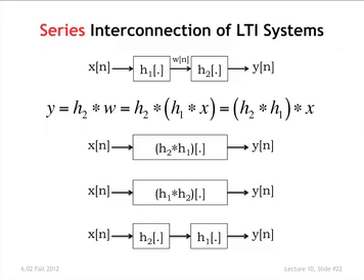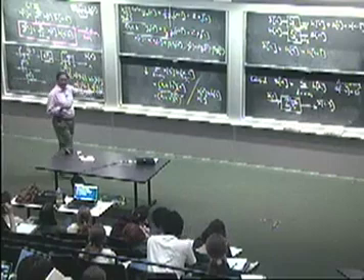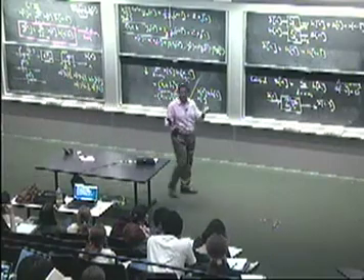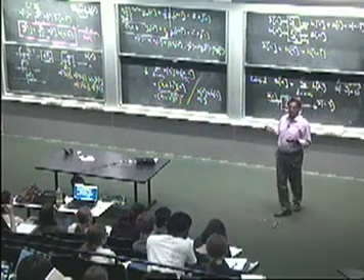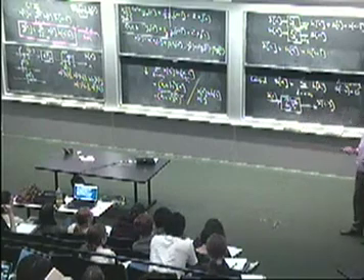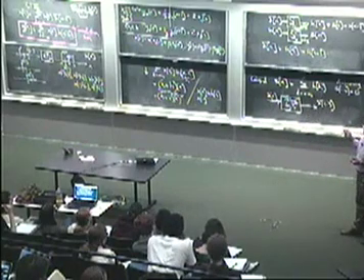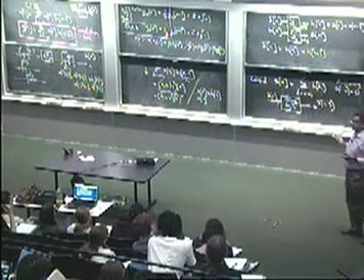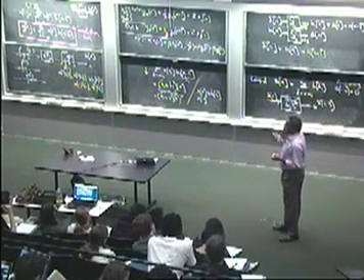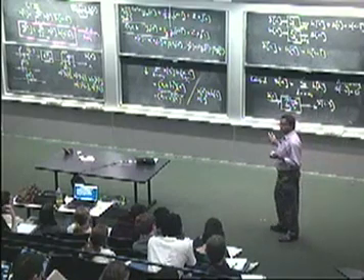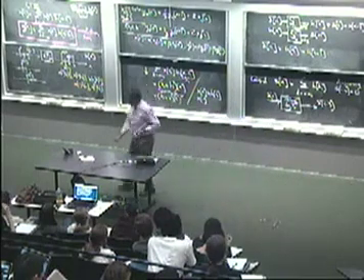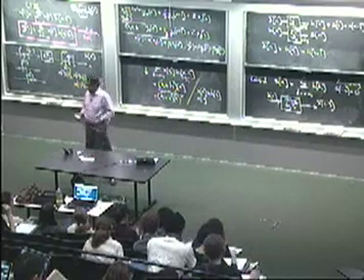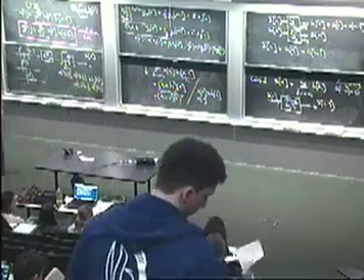So from here, you can go to this, which then tells you that if you've got two LTI systems in cascade, the effect on the output is the same, whatever order the systems are connected in. You might ask yourself whether the same is true if this was linear but time varying. And you should hopefully find out that in general, for linear but time varying systems, you can't do this. So really, linearity and time invariance is what it takes to attain this. Okay, let's leave it at this for now, and we'll pick up again. You'll pick up some in problem set 4 and also next week.